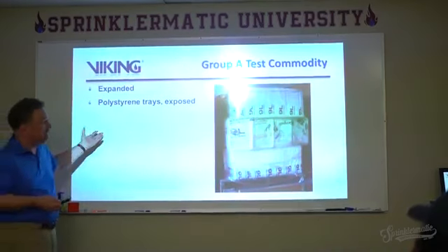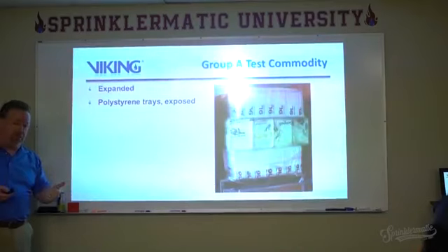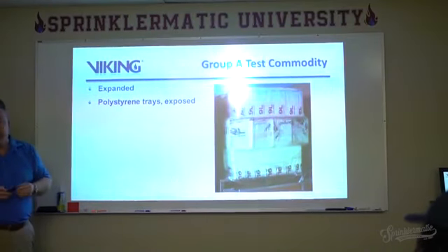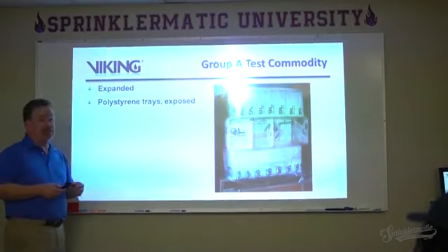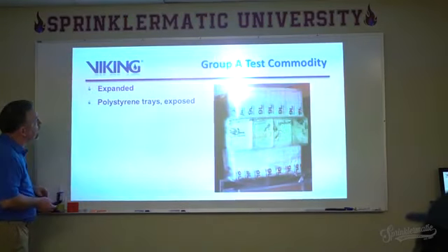In fact, they are the biggest commodity challenge as far as protection is concerned, because the plastic burns really, really well, and it's infused with air, so it's got a natural supply. So we need to wind up with some pretty serious fires here, and a big challenge for our sprinkler system.